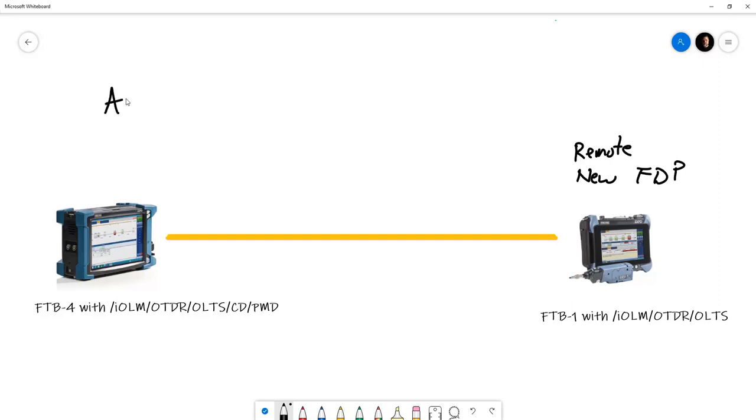Over on the A side, we have a legacy site. So this switch or hub has been here for years. It has old panels. It has ST connectors, right? It has a lot of issues with just years of contamination of these connectors. And so just cleaning and inspecting the connectors on the A side might take quite a bit more time to get the level of performance that you need to qualify for a test. So there's a lot of different levels of challenges here.